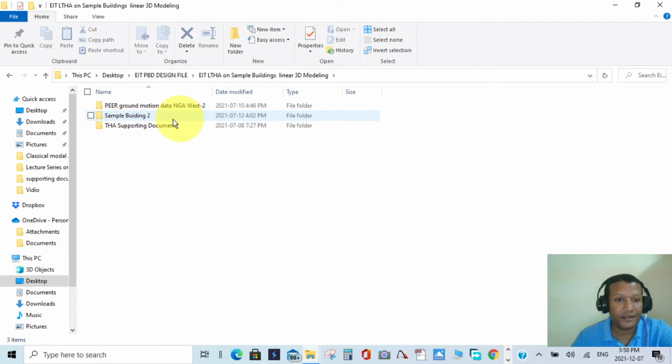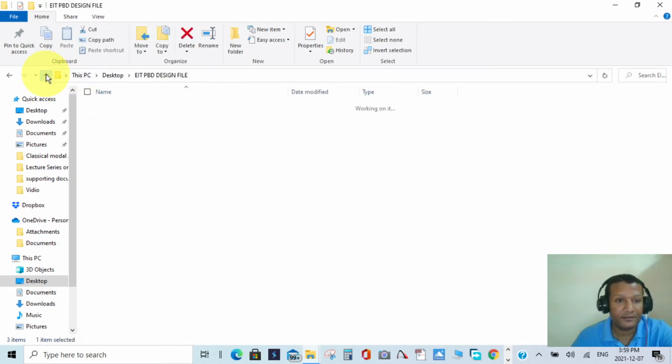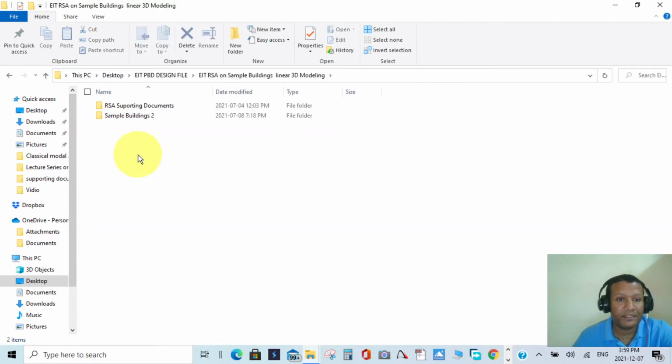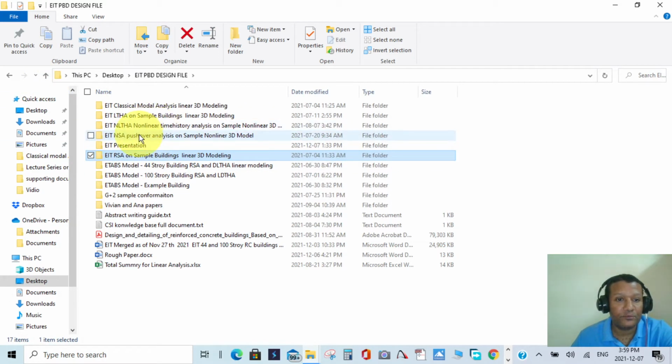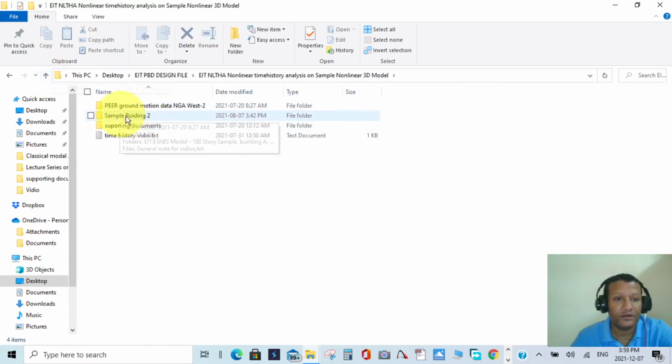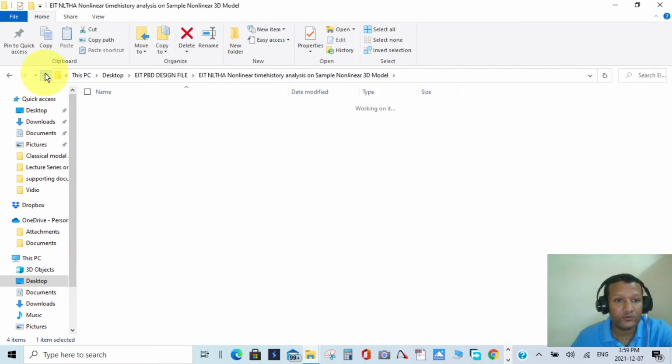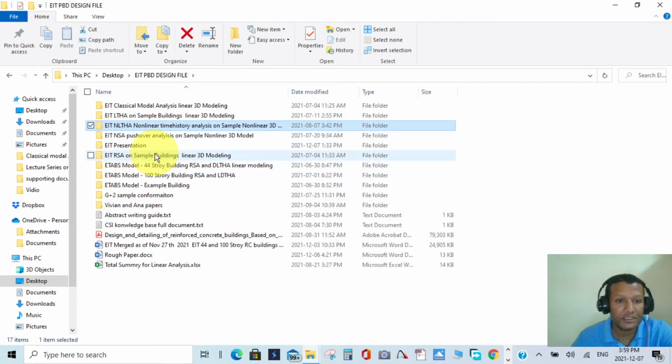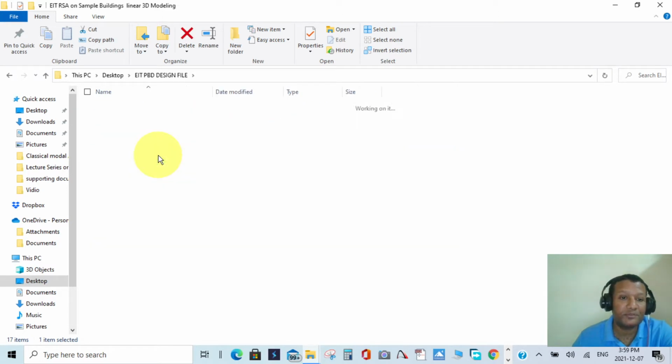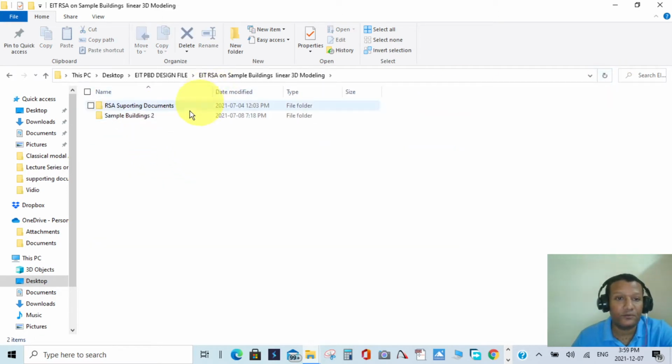Again, linear time history, the same thing, 44 and 100, and response spectrum analysis also the same thing, both 44 and 100, and pushover analysis and nonlinear time history analysis also. We have 2 buildings, and I also have a video on that. In this part I am going to concentrate on response spectrum analysis, and we have 2 buildings, 44 and 100 story buildings, and we will see.